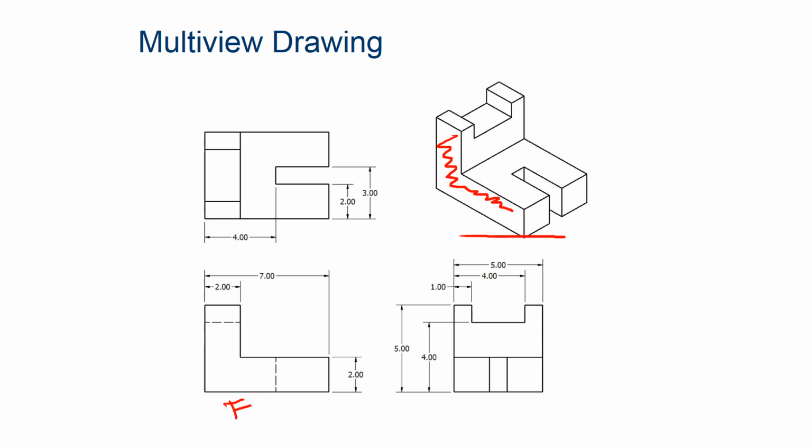Sometimes those rules can be broken, all right, because we have two hidden lines here, and it's really the only hidden lines in the entire drawing. So I see the hidden lines here and here. We broke that rule because when we look at it from the top, it's kind of blocky and doesn't look very much different from the side view. So the top looks very similar to the side view, and so the front shows us the most information. So remember that. And so there's the side.